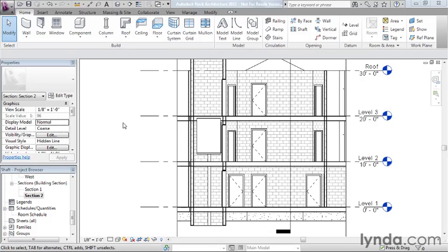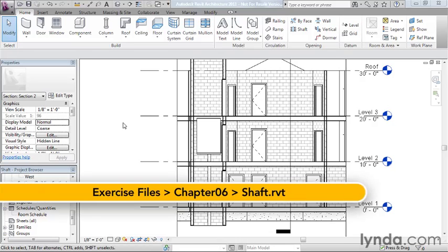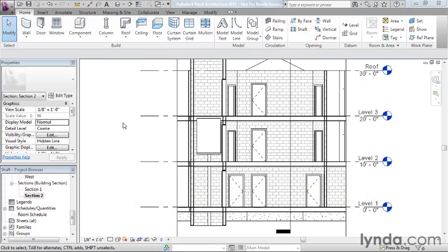Once you have your basic geometry in place like walls, floors, and roofs, you will begin the steady process of refining your model as the design progresses. In many cases, you'll find that you need to cut holes in some of these other items, like simple passageways, or shafts for stairs, or shafts for elevators and equipment, or even skylights for dormers and roofs. In some cases, it might be easiest to just edit the sketch to represent that penetration. In other cases, you'll want to create an opening object.